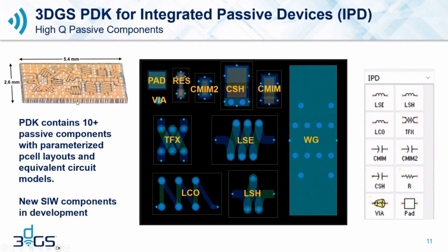Over here on the left is a typical product that one of our customers designed. It is a bandpass filter from 3 to 5 gigahertz. You can see the 3D spiral inductors in the substrate, along with the BGA footprint solder balls. This will be flip chipped over onto a PCB and reflowed.